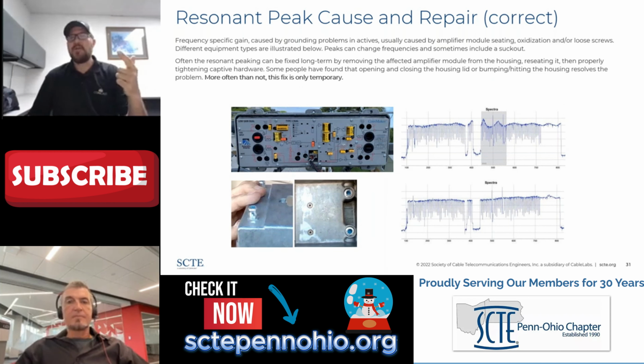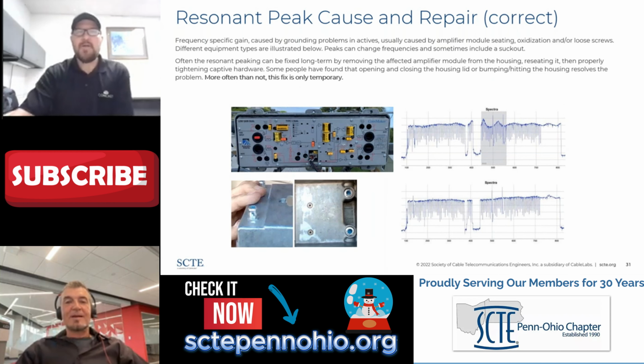They're often a result of corrosion or improper tightening of the module into the housing, or they could be warped housings and/or modules that don't allow for proper tightening and mating inside the housing. So more on resonant peaks, causes, and responses is in the OP280 document, but this is a really good illustration of what a resonant peak can look like, and what the resolution is.